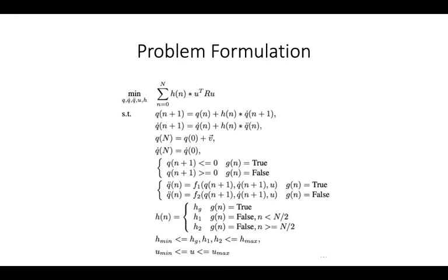To further help the nonlinear solver, I gave it a predetermined mode schedule of when the hopper would be in contact with the ground. This allowed different time steps to have different dynamics constraints corresponding to the different conditions of being in the air versus in contact with the ground. Additionally, 3 different time steps were used as decision variables, corresponding to before, during, and after contact with the ground. This allowed the solver to stretch and shrink the contact to the required time while also placing it in the correct location relative to the start.